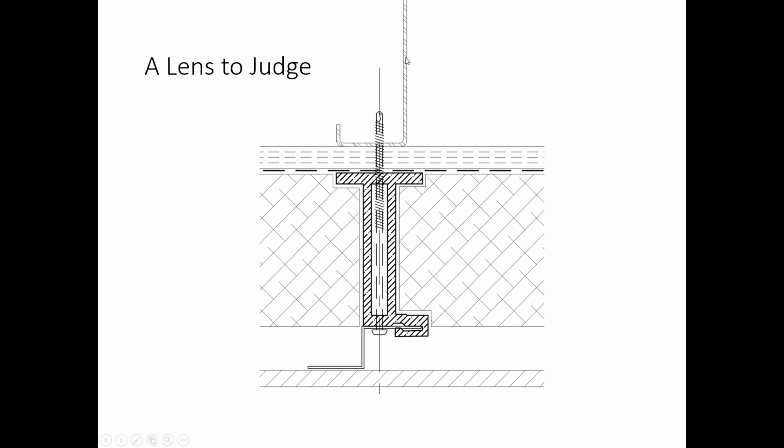And if you can do that without lifting your pen, you know that you have a metal to metal to metal connection and you have fire safety by observation. The fiberglass could become damaged in a fire. Whether it really does or not, it doesn't matter. It could become damaged and yet your cladding would stay attached to the building without a doubt.